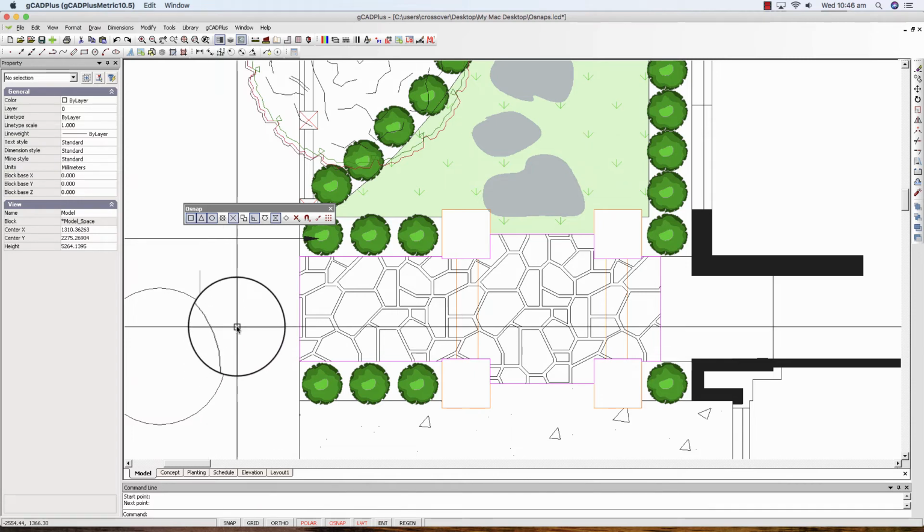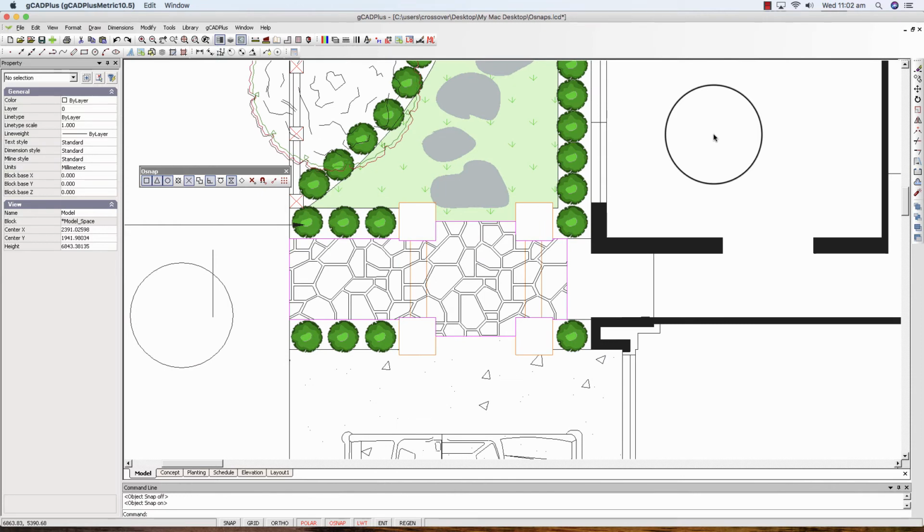So I hope that helps in showing the power of running with lots of Osnaps, but you really do want to be able to turn them off, all off, and then all back on again with a single keystroke. Well, I'd like to add a note that a little reading tells me that on a Mac you can set the keyboard to behave in such a way that the F keys behave as they would on a Windows machine, and I've done just that.